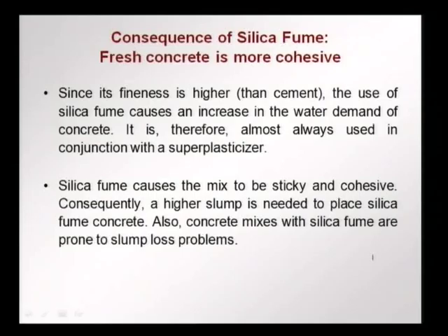So, what are the consequences of silica fume? In the fresh concrete, we find that silica fume concrete is more cohesive, that is, it is more sticky. Since the fineness of silica fume is higher than cement, we have to have more water, but this obviously will hurt in terms of strength and durability.